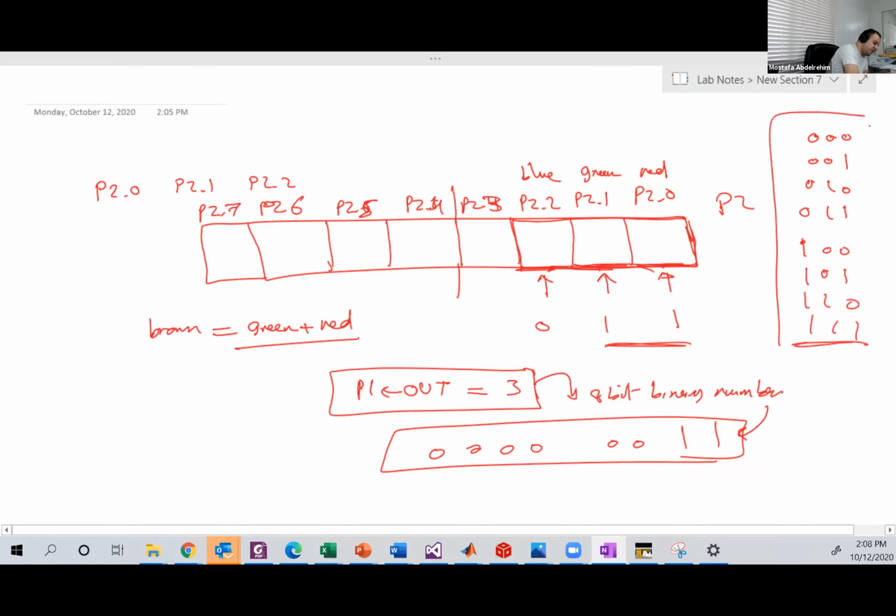You have these 8 bits, and you don't need hexa. You can just use decimals. That's fine. So basically, see what the equivalent decimal number of these 3 bits is, check your required color, and just send that number using this line, and that's it.